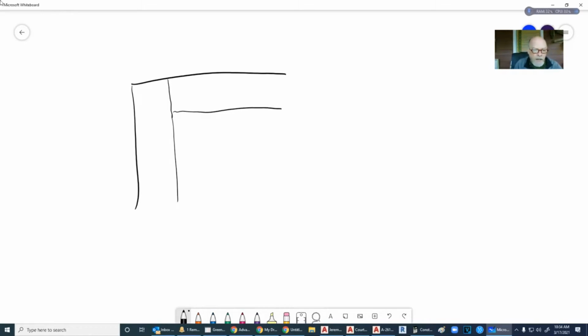Bye. So we're looking down on this, and conventionally, we would have a stud, we would have a spacer, we would have another stud on here, and then we have the stud in the butt wall. And then we've got just this little bit of area right here that would be used to put a drywall on. We got to make sure that we put this piece on before we put this piece on. So, you know, this is old school.